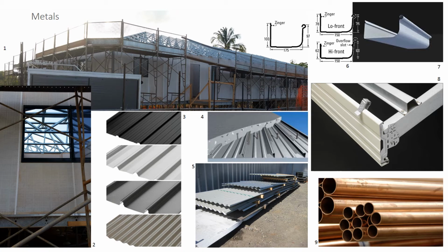Ferrous metals are those metals that contain a large amount of iron. They have magnetic properties. The main types of ferrous metal are cast iron, wrought iron, and steels. Generally, most non-ferrous metals are more costly to produce than ferrous metals. However, they often have much better working properties and resistance to corrosion. The more common non-ferrous metals are copper, aluminium, zinc, lead, nickel, tin, and cadmium.